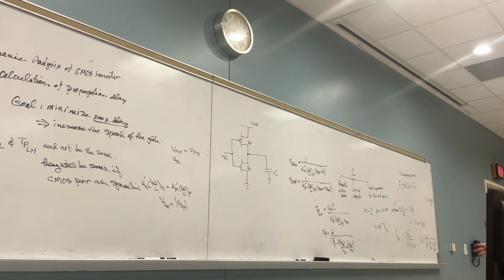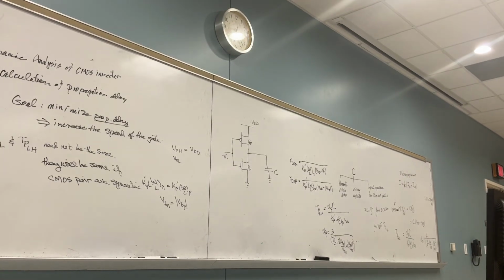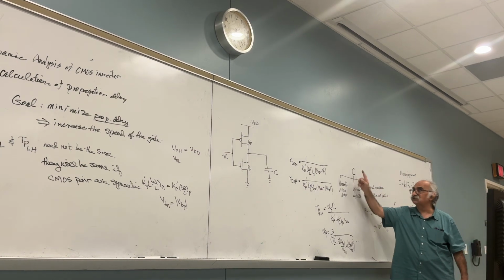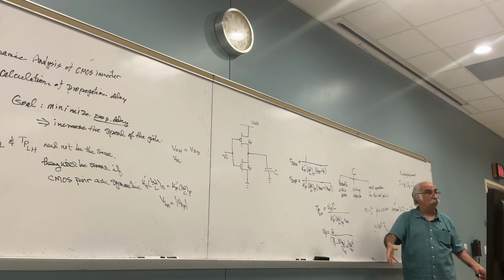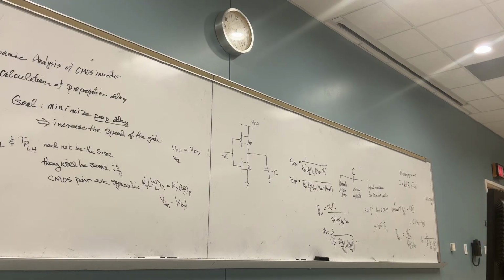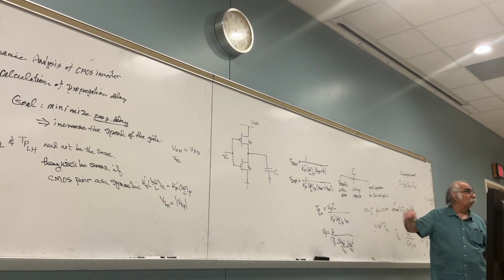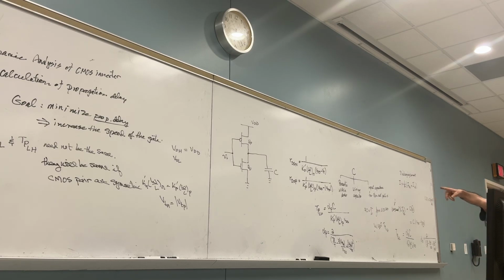Clear? That's a dilemma. And the design of the dynamic operation of the CMOS has many contradictory components that you need to take care of. The whole idea is that you have to remember that C is a function of area, if you make your wiring properly when you lay out your circuit. Limit the number of gates, the number of inverters. Also limit the number of inputs.